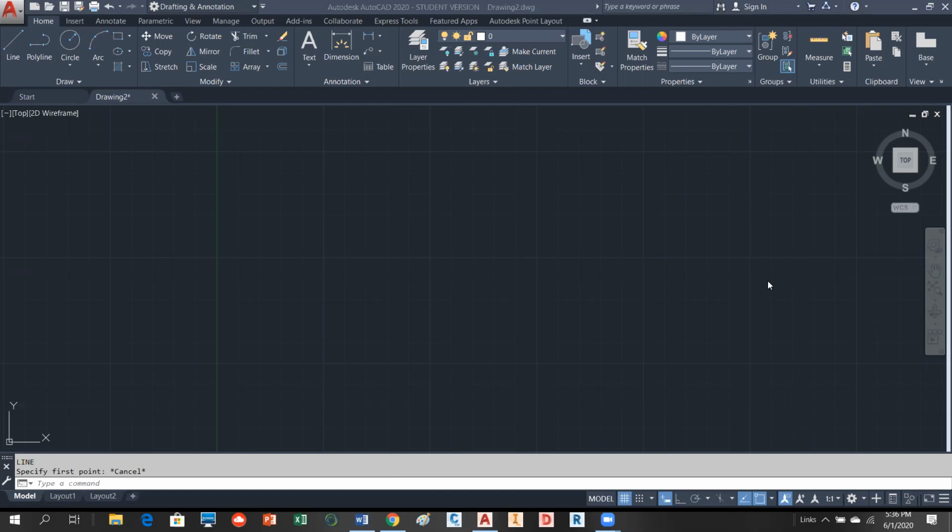All right, a couple of other areas, and then we're going to start to look at a couple of concepts here. This area down at the very bottom, right above my taskbar, you have tabs here. This is called your model tab and your layout tab. So there are two dimensions that you can work in AutoCAD. What's called model space, which is the model tab. And there's only one model tab per drawing, or one model space per drawing. So that is where most of the action happens. When you go to print or plot a drawing, and you have a complex title block and other textual information, those kind of things, then you can create what's called a layout.